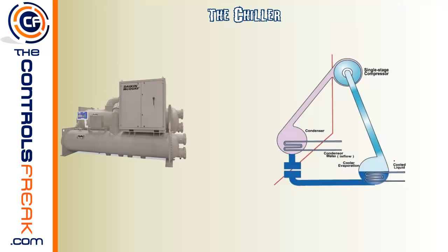One other thing to note about chillers is that in these barrels that you see here, there are many different bolts that come across here that seal up the 2 ends of this barrel. Inside the main portion of this barrel, these water lines that you see here are actually long tubes that run the full length of the barrels. And so if you ever hear somebody saying they were changing out tubes or they have dead tubes in the barrels and so forth, these are the tubes, and there's many of them.